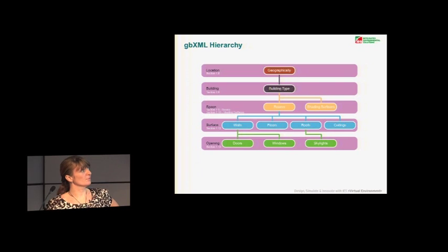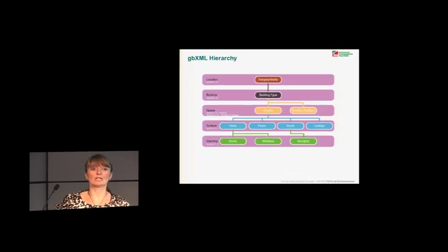We have rooms themselves, which is obviously critical. For analysis, we need bound volumes, and this is going to be key. And for those of you that have been looking at the integration already, you'll know that there are certain rules to follow to get those rooms to come across, which you can then perform your analysis on. If the rooms don't import for whatever reason, that creates an issue, because then we've effectively got a hole or a gap in the model. So when we run analysis on that, the room adjacent to that hole sees that as an external zone, if you like, which will then affect energy flows through the wall that separates the two. So rooms are critical.